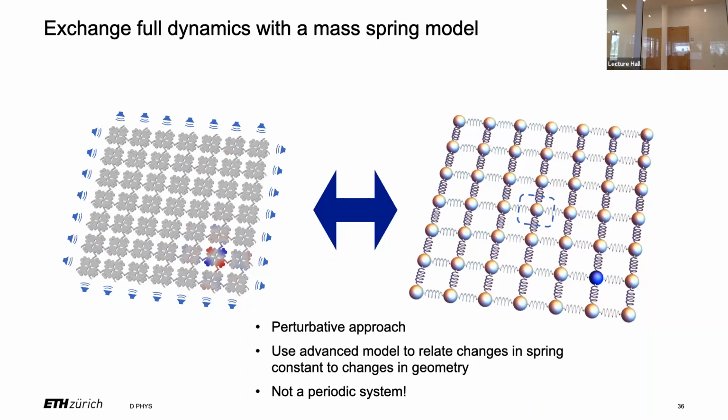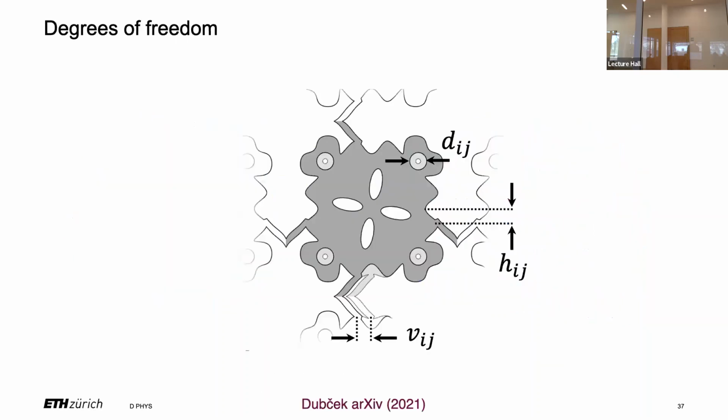So using the same kind of technology here, that's what you do. You design the degrees of freedom as holes. That changes the local frequency, because this thing deforms, and if you make a hole, it's less resistive towards bending, and B, it has different mass, so there is an effect on the local frequency. And then the position of these couplings changes the vertical and the horizontal couplings, depending on where it is.